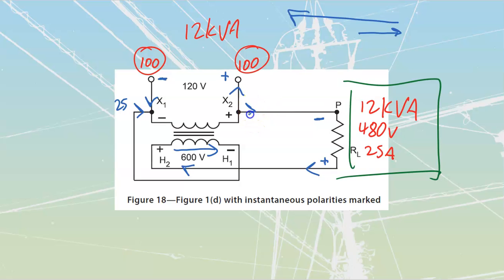We've got this 25 amps that we have already done the analysis for, that it's going to have to go through like that. We've got this 100 amps entering in over here. 100 entering a node plus another 25 entering a node means that I must have 125 amps that is going to be heading through. That 125 enters into this node, where it splits off into the 25 as well as into the 100. We do satisfy Kirchhoff's law of current.